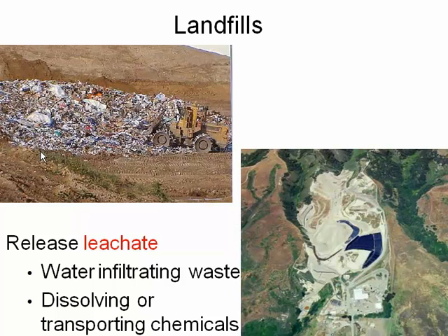And finally, if you think about everything that goes into a landfill, all the different things that you throw away or you've seen thrown away if you've gone to the dump, all of that material, while covered with liners to some degree and buried under soil to isolate it from the environment, historically has still been connected to the hydrologic cycle by virtue of rain infiltrating through the soil cover into the waste, and then causing chemical reactions that will dissolve and cause the transport of those chemicals.